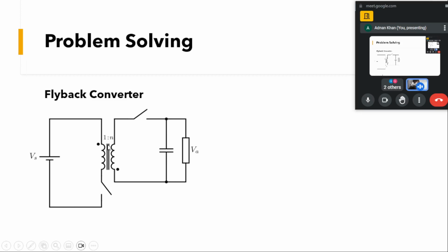Here we cannot say this is a transformer, this is usually a coupled inductor, because in a transformer the flux changes, we have an induced EMF at the output due to the primary, and there is a continuous transfer of energy. But here we have two devices.